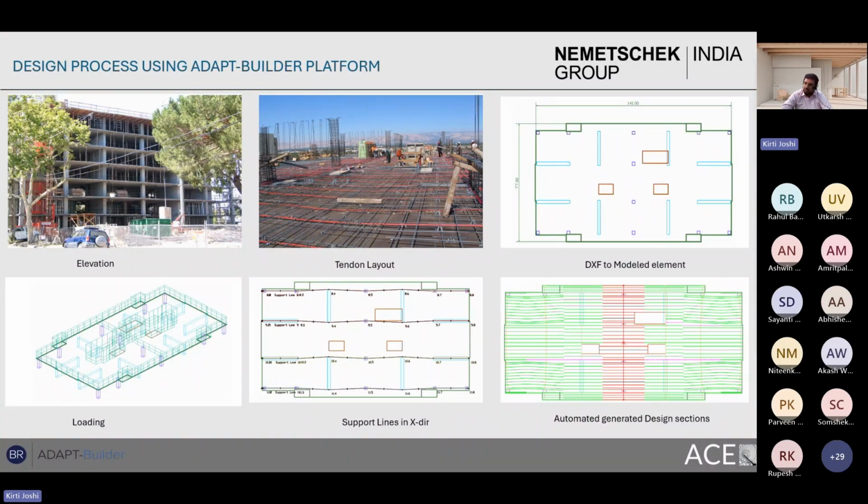Like I mentioned, you can use the modular features or the transform features of the program to transform the polyline into the structural components. And next, you can apply the loads and select the areas of load, such as the balconies, or even specify the special load case. And depending on the design code, you can select the program to generate the appropriate load combination.